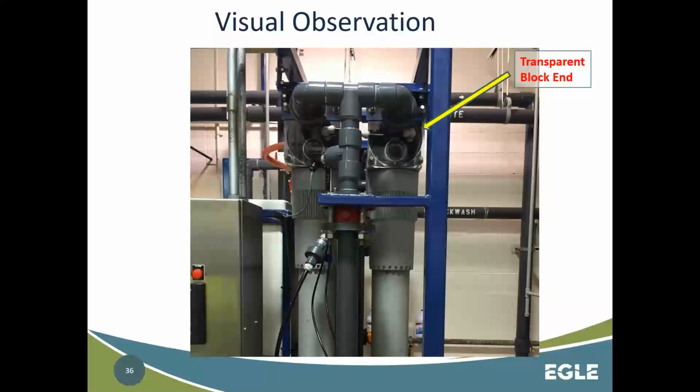And so on that sonic testing, I mentioned the stethoscope. What I've been told by operators, and how they were trained by the manufacturers, is they'll go through module by module. They'll take the stethoscope, listen here at the top, listen in the middle, and then listen down on the bottom, and then go on down to the next one. It's a bit tedious, but if they hear bubbling, then that one has got to come out and they identify where the breach is and pin it off.